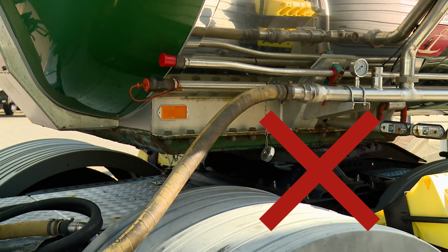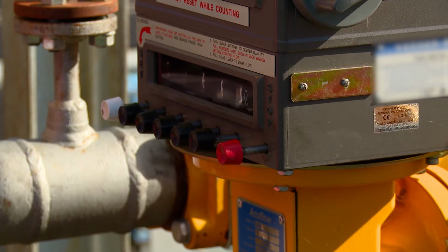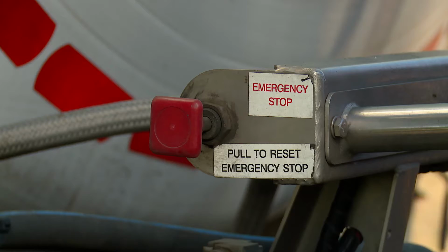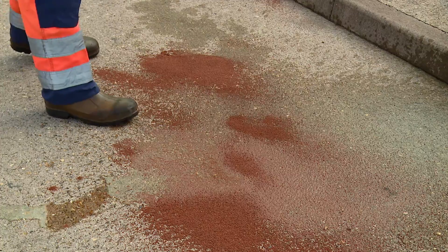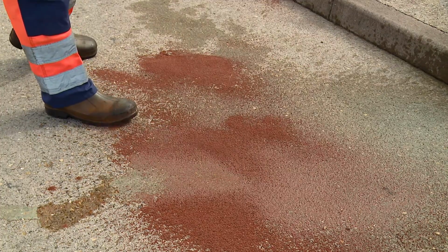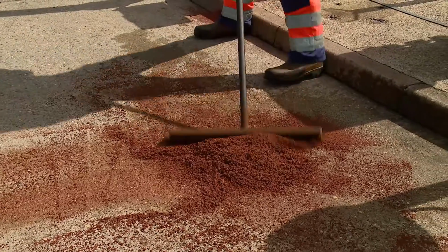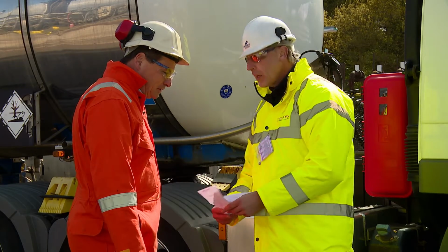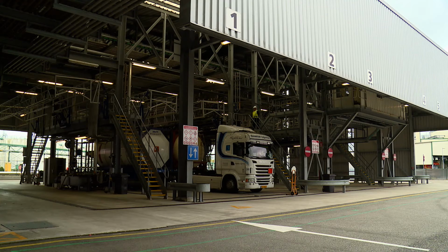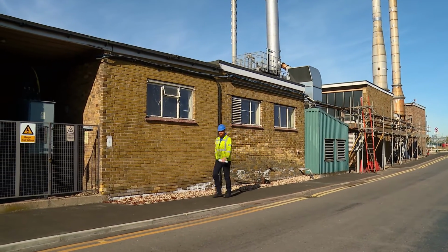Under no circumstances must solvents be discharged using compressed air. In the event of an emergency where the transfer needs to be stopped, drivers and operators must be aware of site emergency procedures. If there is a spillage, report to your site host immediately for advice. All incidents and accidents must be reported to a site employee. Assess the risk of continuing with the transfer when safe adjustments have been made and site personnel have agreed it is safe to proceed. Pedestrian access around the road stand should be restricted and walkways used if available.